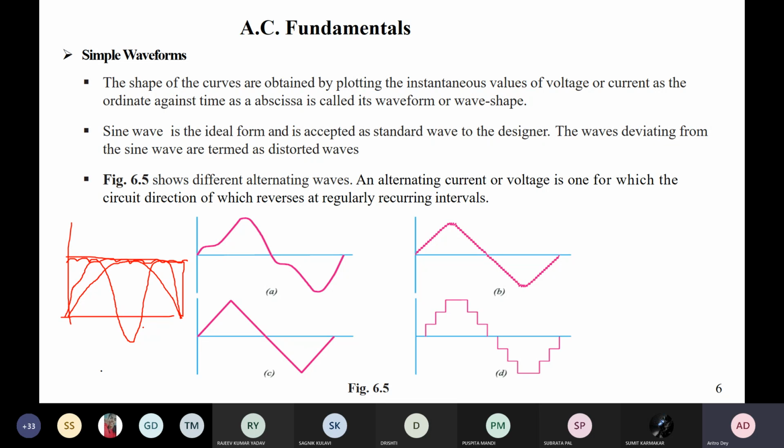So the more it is distorted from the sinusoidal, the more number of harmonics will be present. Whatever we can see here, we can represent in terms of n number of odd and even harmonics. We can go till as many as possible, but once the amplitude of that harmonic signal is small, we can ignore those things.